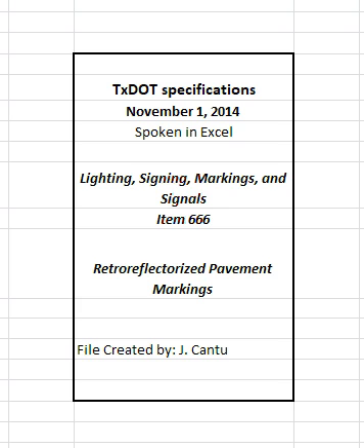4.5 Retroreflectivity measurements. Use a mobile retroreflectometer for projects requiring minimum retroreflectivity requirements to measure retroreflectivity for contracts totaling more than 200,000 feet of pavement markings, unless otherwise shown on the plans. For contracts with less than 200,000 feet of pavement markings or contracts with call-out work, mobile or portable retroreflectometers may be used at the contractor's discretion.